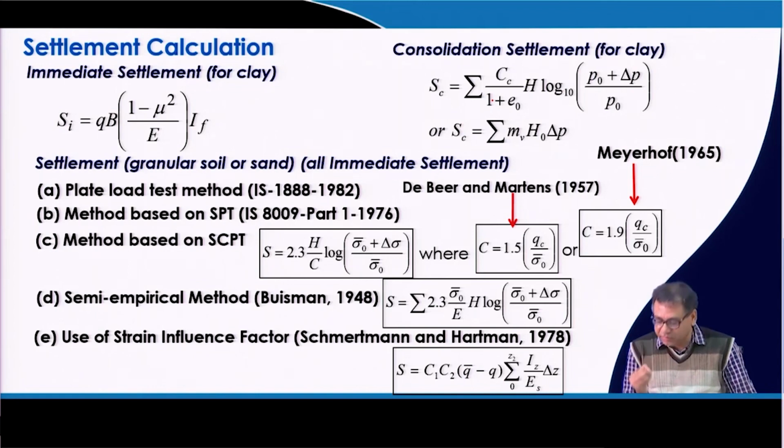So, most of the settlement will take place immediately. These settlements can be mostly calculated from field test data. I can get the settlement directly from the plate load test method, from the SPT-based method, and from the SCPT-based method, that means the static cone penetration based method.